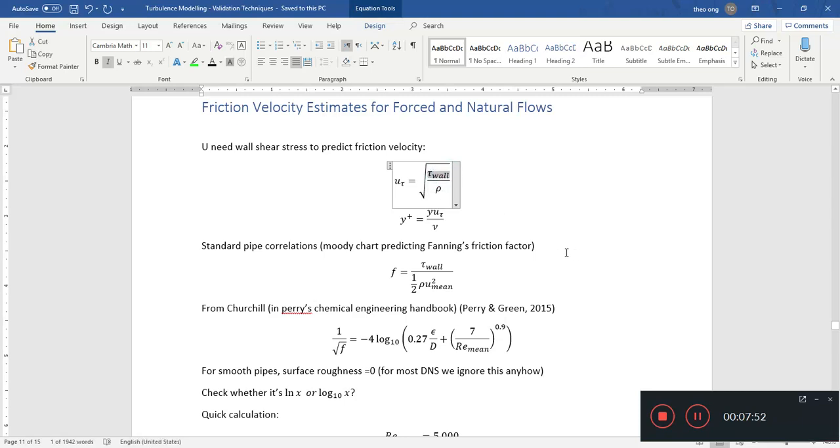All right. So this will give you an estimate for the wall shear stress. It's not like you just do it once and then it's fine. You still need to check your CFD or whatever for your real wall shear stress, in order to see whether your units are right and the grid is fine enough. So you look out for your mean wall shear stress, and that should give you the right units, or maybe your maximum wall shear stress if you're that picky.